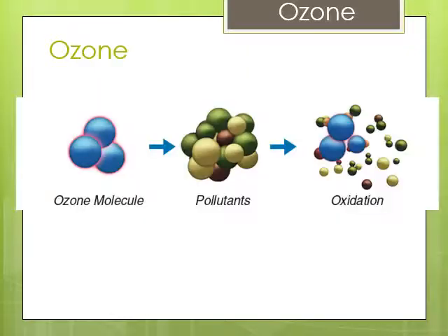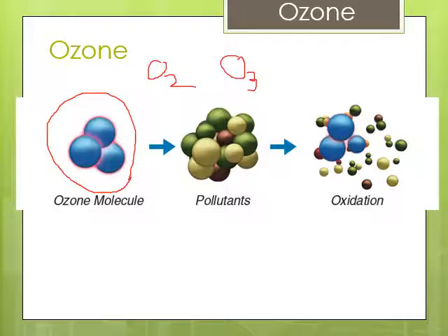But typically it is set up so that basically you generate ozone using electrolysis and oxygen. You bubble air through your water and you apply a high voltage, and the oxygen, instead of being O2, will recombine to O3, which is ozone, right? And you do that using adding electrons with these high charge plates and bubbling air through the water. And the ozone, which is fairly water soluble, actually reacts not just with living organisms, but biological material like biofilm. And as it reacts, it breaks it up into smaller pieces, which then flush away and are caught in your filter.